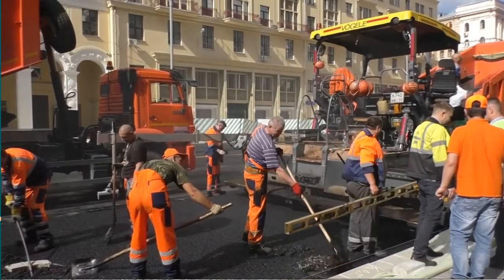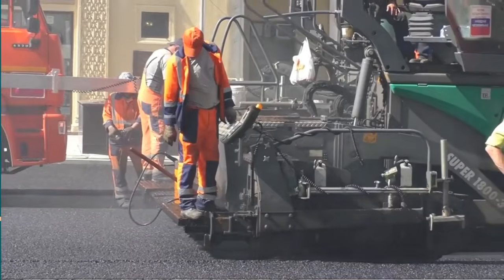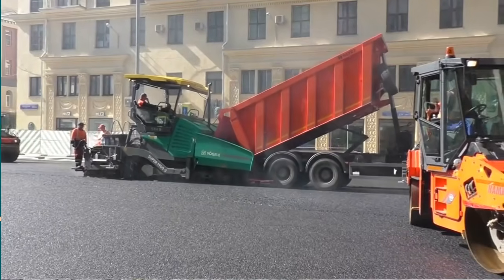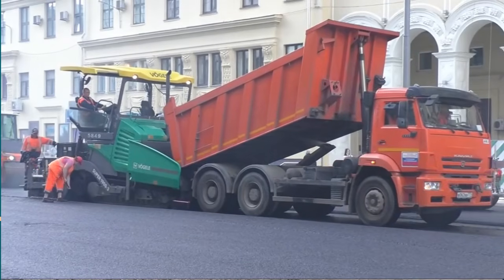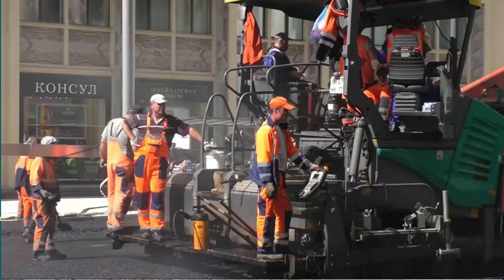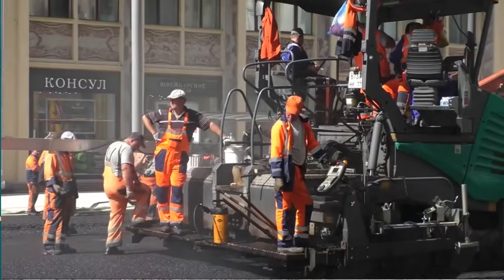The automatic sensor shall ensure that the mix is being laid to the proper line, grade and level. This sensor of the paver will be guided by the string lines fixed by surveyors with the stake and arms on both sides, 0.5 meters away from the edge.